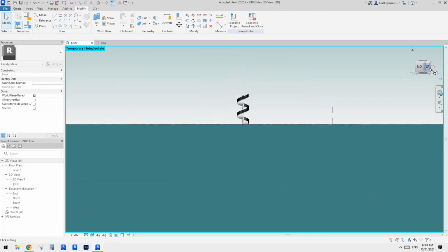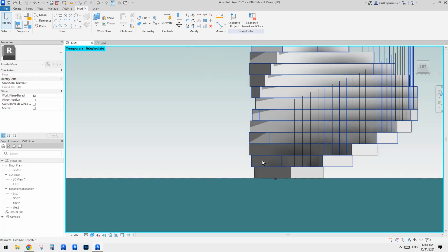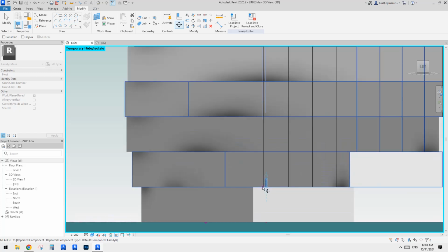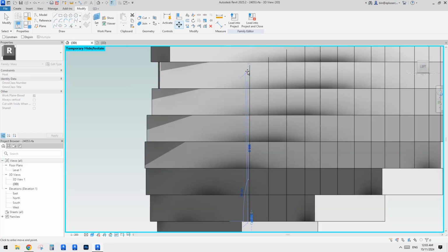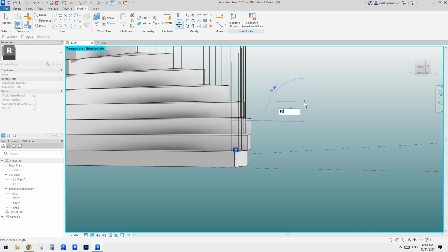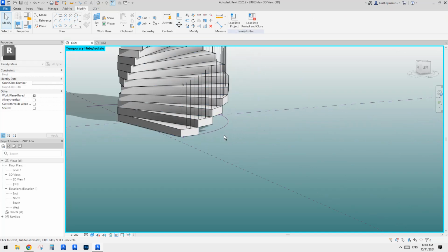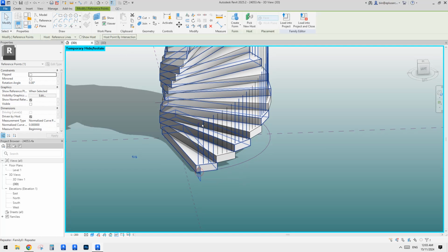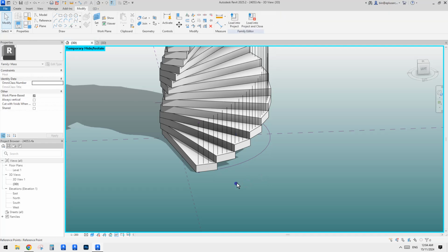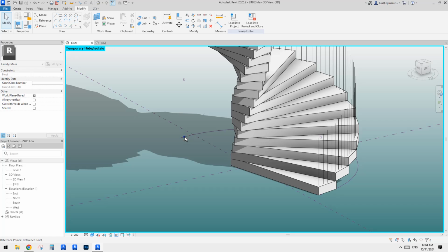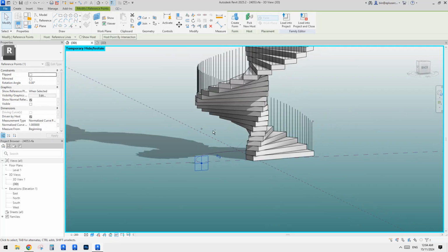Let me just go to the right hand side. Where's my profile? Here. All right, so select it. I'll just move this up to match. It's not, let me, oh, looks like 1 meter. That's fine. We can maybe just move it up by 1 meter. Okay, oh good. And then we just need to select this point together with the profile, CC, and select the point and use pick new host. So this time we're going to place this one on this end.